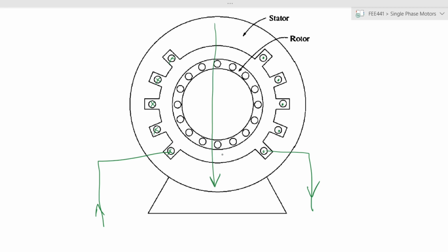All right. Now, what happens when you apply a single phase to a motor is that the only thing that will change is the polarities. Your only alternative would be either these currents are flowing into a winding or out. They can only be in one of two directions or polarities. So you will find that the resulting magnetic field can only be either, in the case of the cross-section that we have here, in a downward direction or in an upward direction. Those are the only two possibilities.